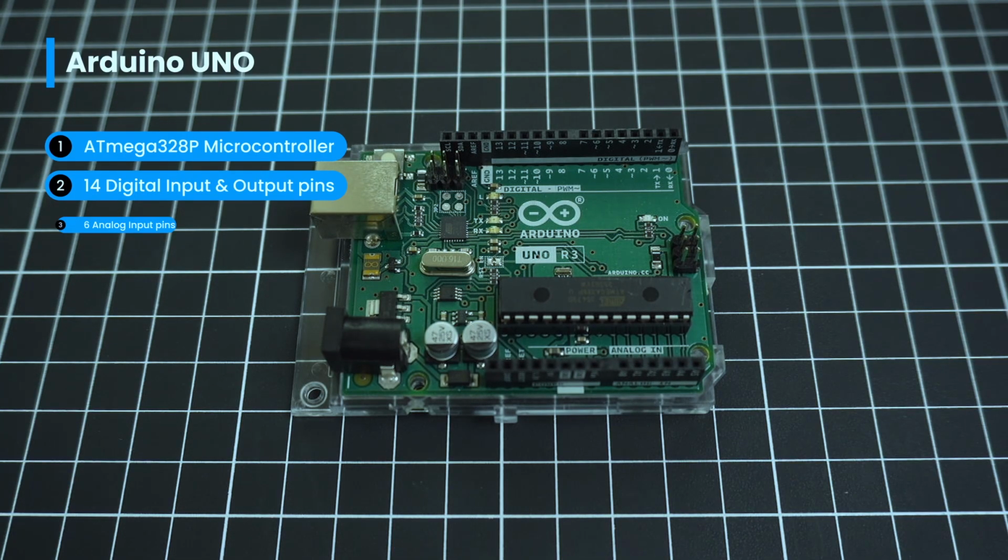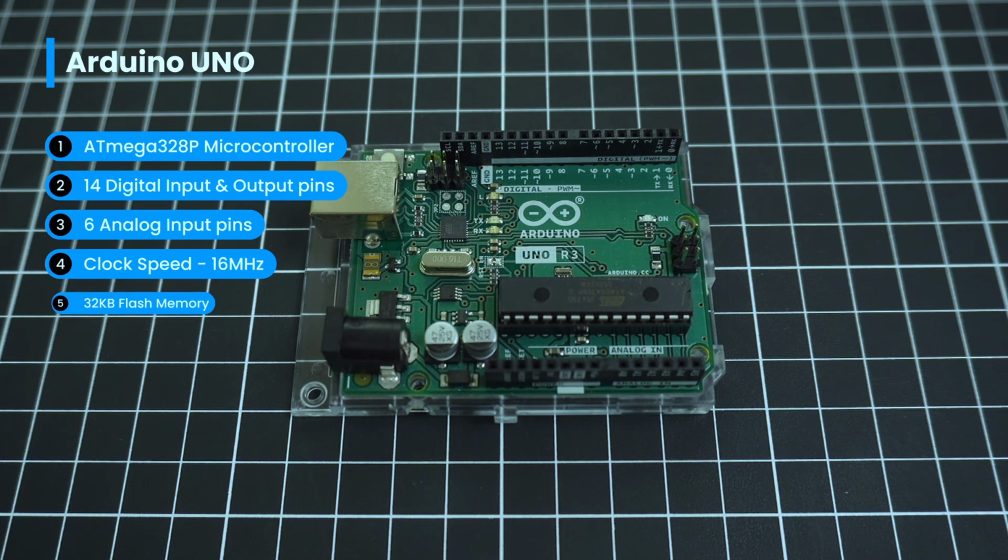In addition, it provides 6 analog input pins, allowing you to read analog signals from sensors such as temperature sensors, potentiometers, or light sensors. The Arduino UNO operates at a clock speed of 16 MHz. In terms of memory, it includes 32 kilobytes of flash memory for storing your program code, 2 kilobytes of SRAM for temporary data storage while the program is running, and 1 kilobyte of EEPROM for storing data that needs to be retained even after power is removed.